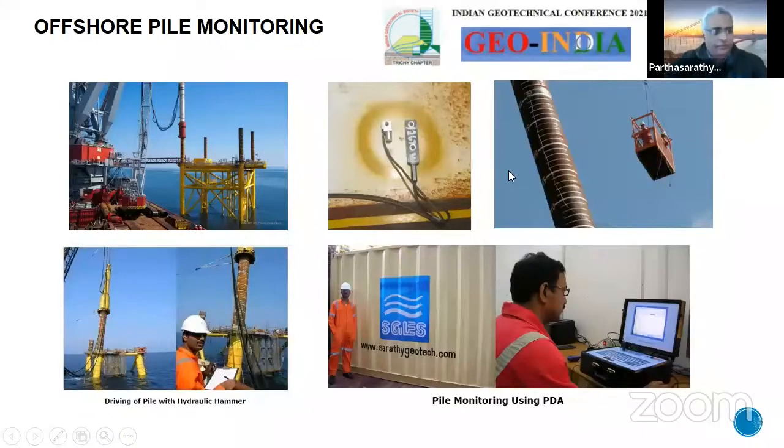There are two philosophies the principals follow. One, if they have the geotechnical data and the piles are driven to the target penetrations, they accept the pile. The other principals want every blow to be monitored and then evaluate the capacity based on pile monitoring. Both of them are in vogue currently in several geographies.